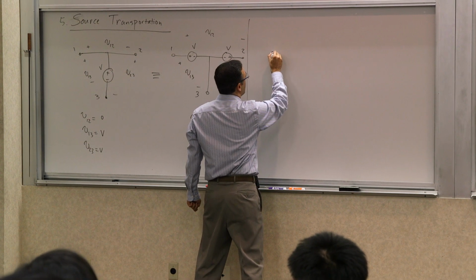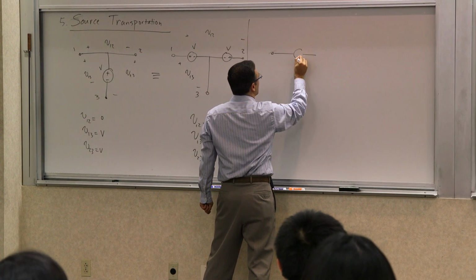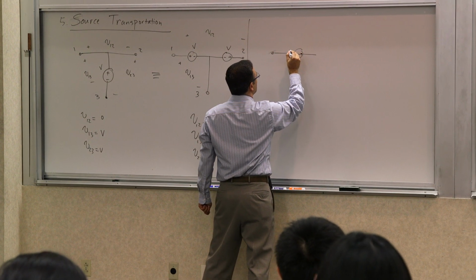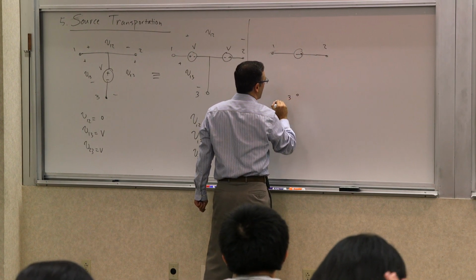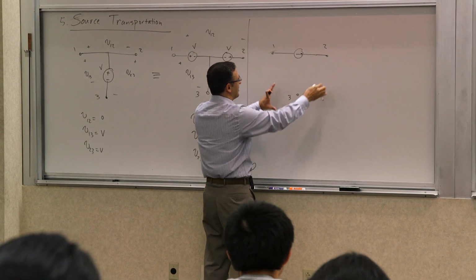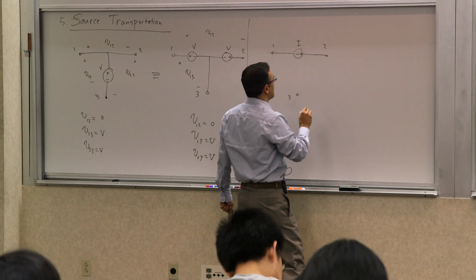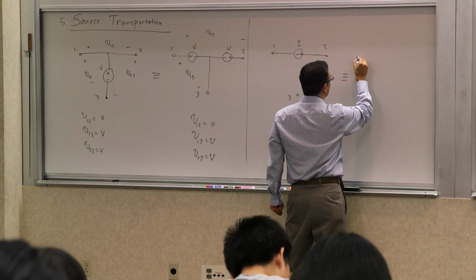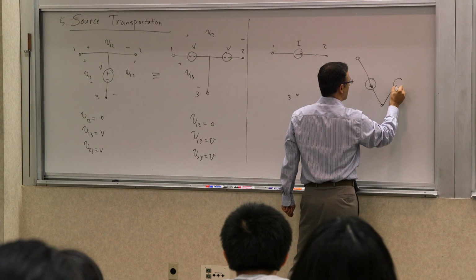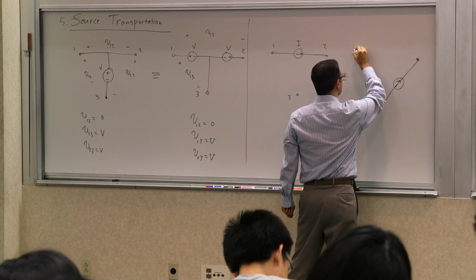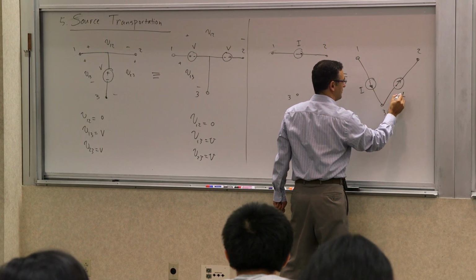So if you have a current source going between, let's say, node 1 and 2. So this is 1, 2. Again, it's a 3-node combination, and 3. And 3 can be attached to other things, but as far as we are concerned, it's this part that matters. This says it's equivalent to the current source being split into 2 currents, 1, 2, and 3, with the same values, I.